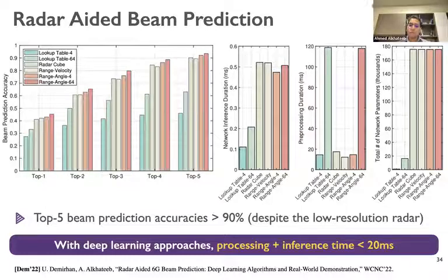But they could always be useful for future or proactive prediction tasks. For example, if we have a sequence of 8 or 10 radar maps from the past, say 8-10 samples or coherence times while the vehicle was moving, then we can probably leverage the sequence to predict the best beam to serve this mobile user in the next 4 or 5 instances.